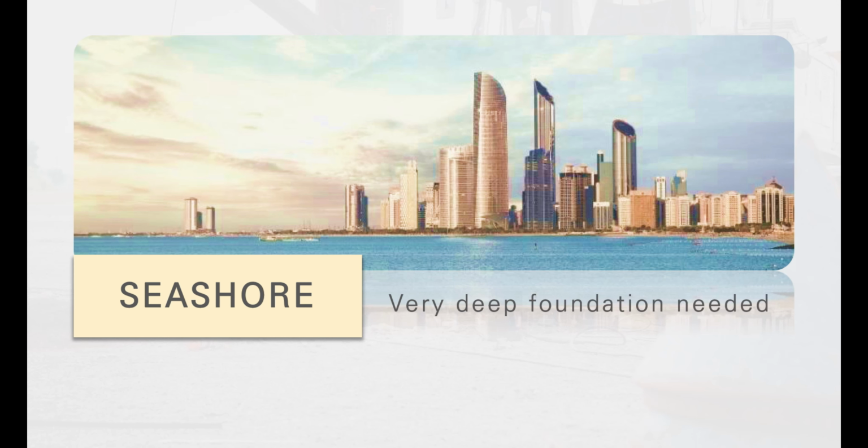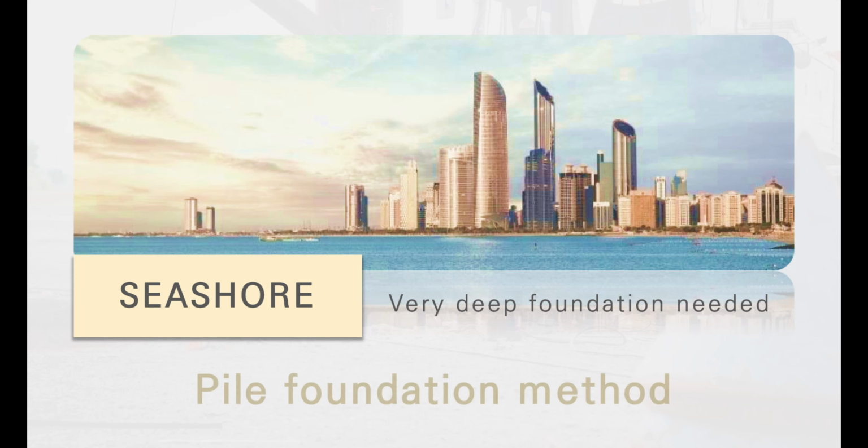It was hard for the foundation materials to get through to support the load, which required a very deep foundation. This is why the Capitol Gate Tower construction used the pile foundation method. Pile foundation is used to insert the piles deeply to the level of hard soil.